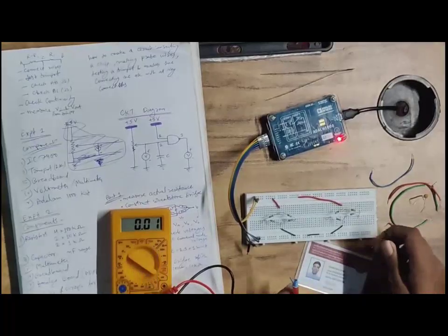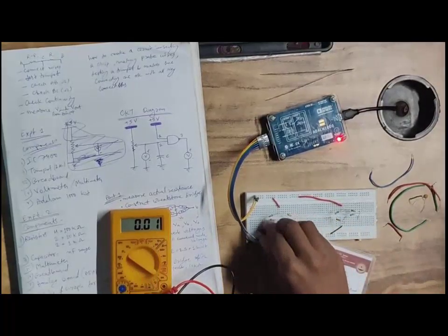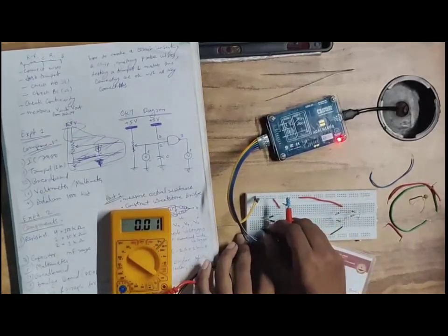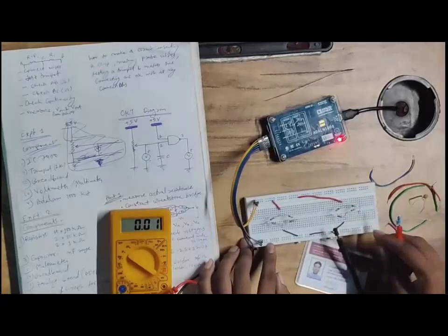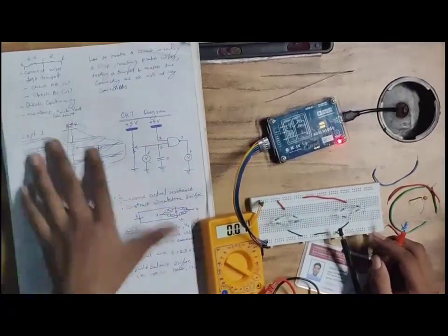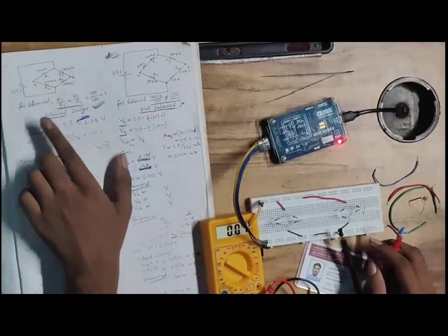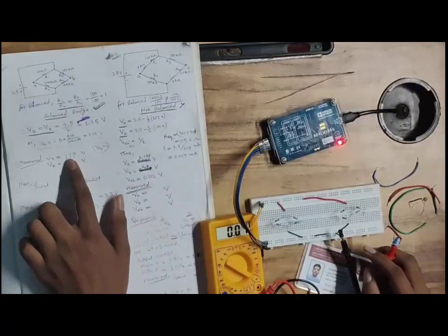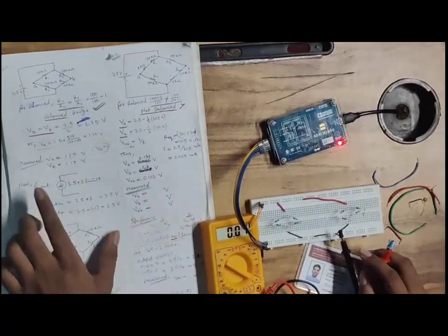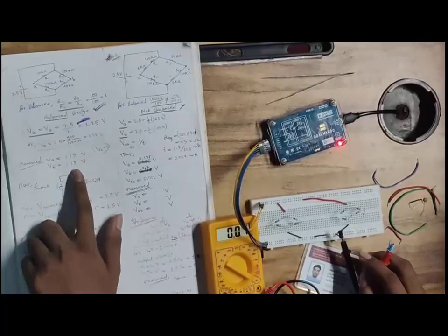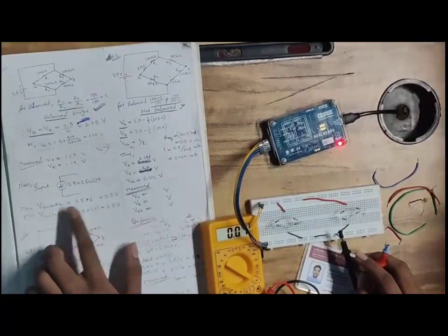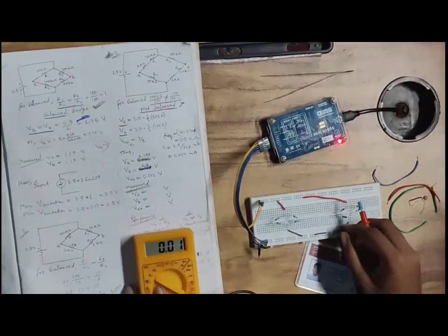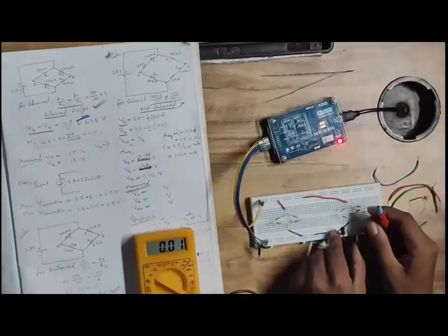This is 0. And now I have done the calculation here, the circuit diagram, and the calculated value is 1.25 volt, and then 1.19 volt is the measured value, and we are moving to the AC part later on. And now we are moving to the second Wheatstone bridge.